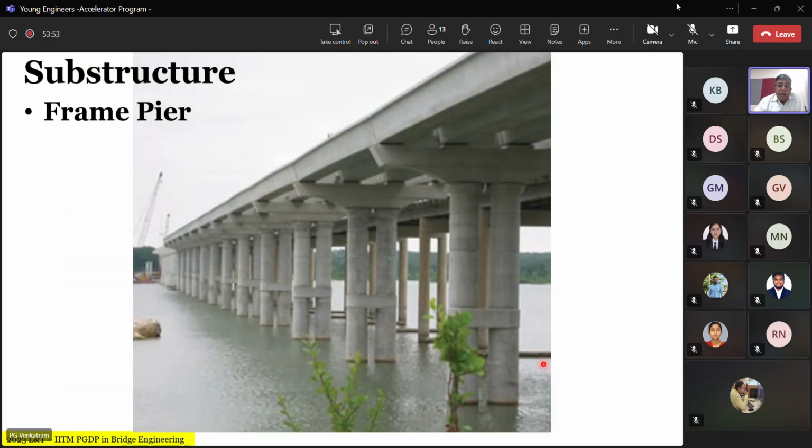So you have other examples of trestle type. These are mimicking cantilever, but in order to reduce the volume of concrete, they have used a concept of a pair of braced cantilever piers with a small bracing at intermediate height and the pier cap, and therefore this is also essentially a framed pier. Behavior might be slightly different than the wall type pier and the traditional frame type pier.